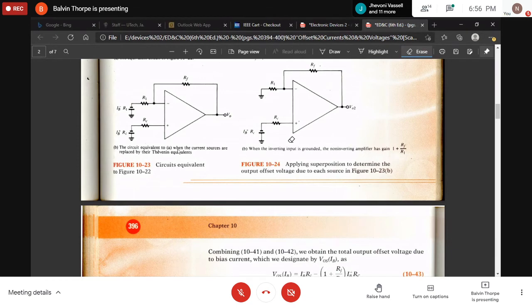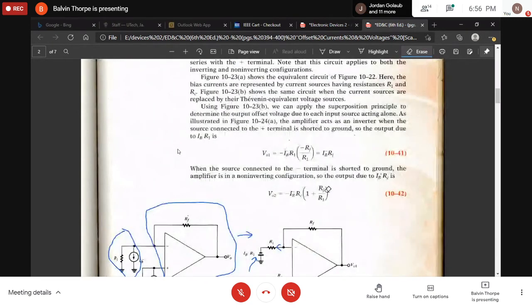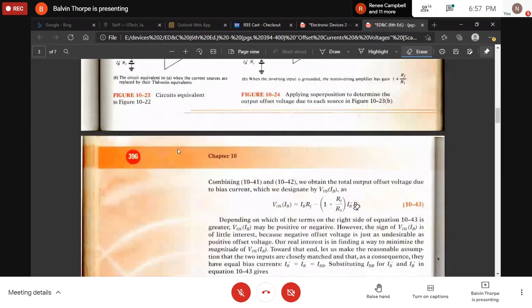And the gain of the amplifier is 1 plus R4. Right. So all of these we have proven so far. Now we have two voltages, VO1 and VO2, that are going to equate to the overall output voltage of the network.